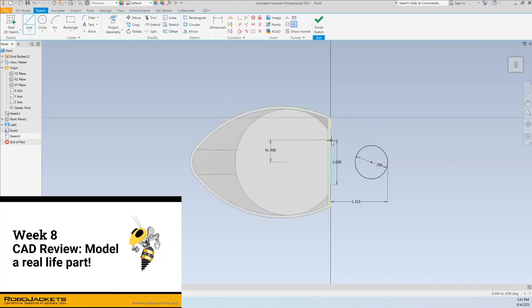Now finally, we gotta just connect these two, so I'll put this line here, and then put this line here. And when I use the tangent constraint, then it'll snap right into place and become fully dimensioned. I don't need to add in a measurement because there's only one possibility of how this ends up.